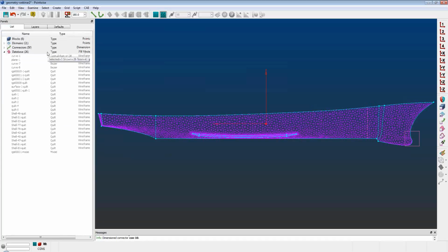Well, with the fault-tolerant meshing, you just don't worry about the CAD. You don't spend any time on the CAD at all, or very little. You just really have to fix the gross errors. You just leave the gaps and the cracks. You go right to the meshing. Ultimately, what you're trying to do is mesh. So it's like, let's just ignore the CAD. Let's ignore the sloppiness in the CAD. Let's get to the mesh, and then fix the mesh.